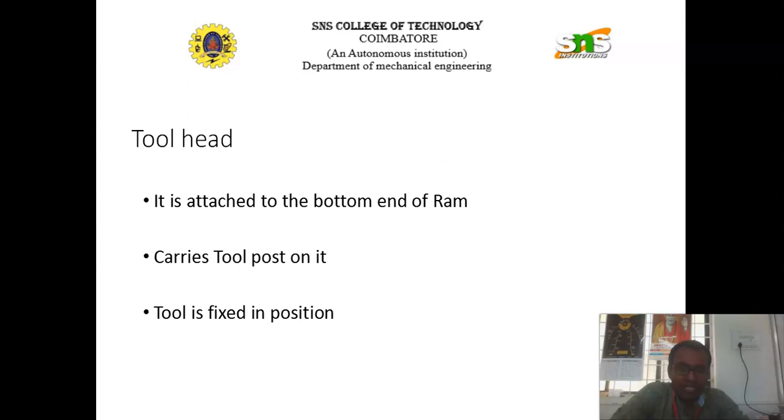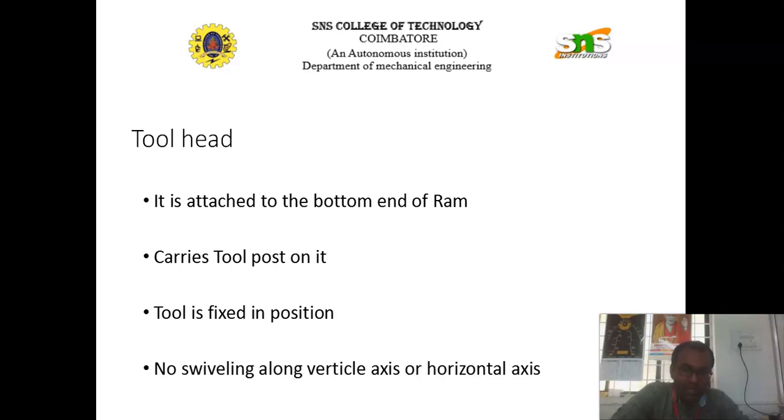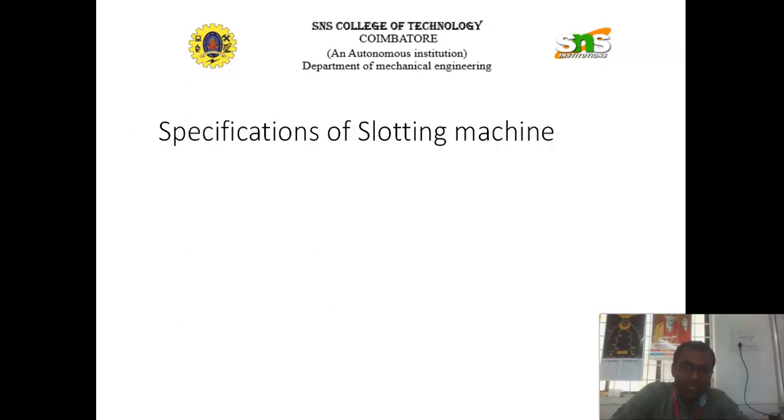The next important part is the tool head. It is attached to the bottom end of the ram. It carries the tool post, and the tool can be fixed in different positions with the help of the tool head, swiveling about a vertical axis or a horizontal axis.